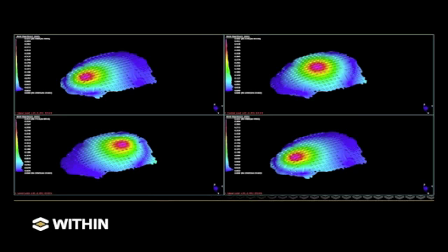Moving on to cranial. Now here, cranial implants are very interesting because if you have a metal implant in your head, it's not very flexible, and your skull tends to be flexible, so it doesn't feel very good. And it also can feel quite cold as well. What we can do is print in a material called PEEK. It's actually an aerospace material, but it's a plastic, essentially. And you can put it in there, and it can have some sort of flexibility, so it feels much nicer. We can also put this lattice structure throughout the part so that over time, your bone actually starts growing through this, and you end up with complete bone recovery through your skull implant.